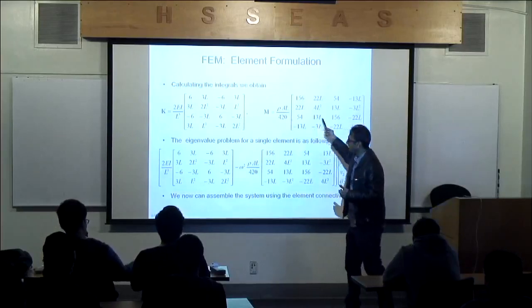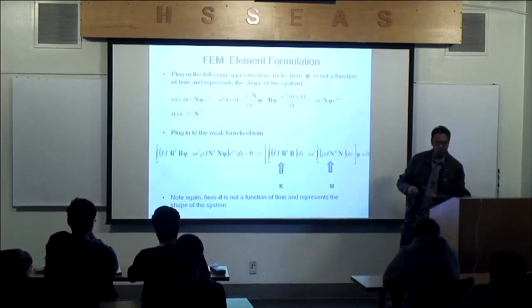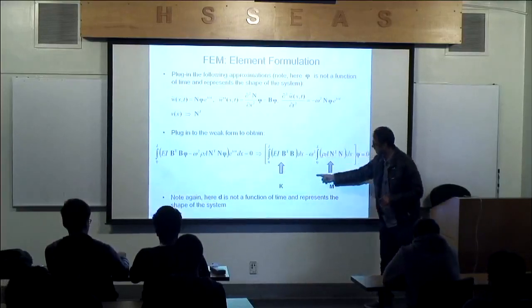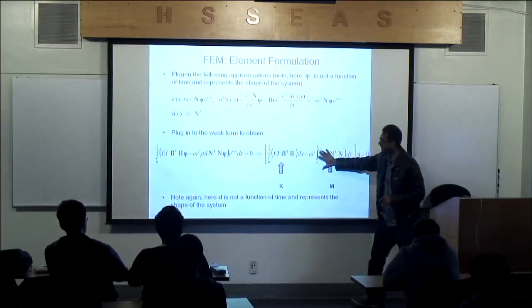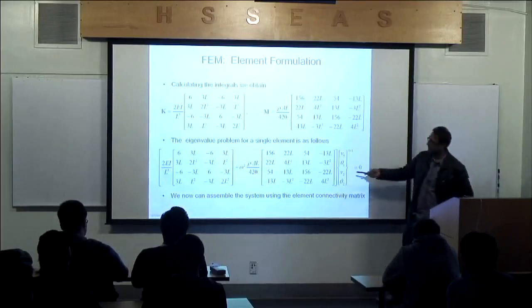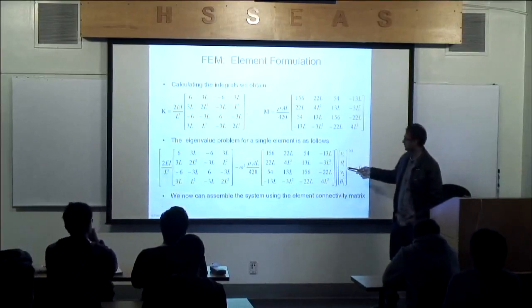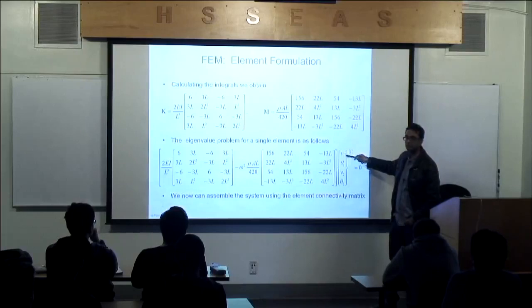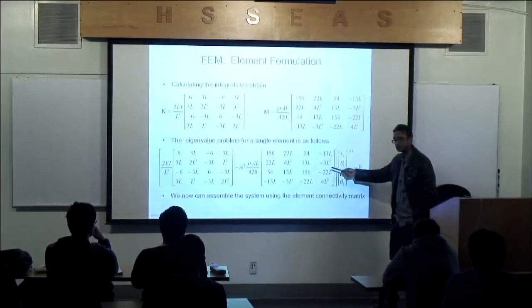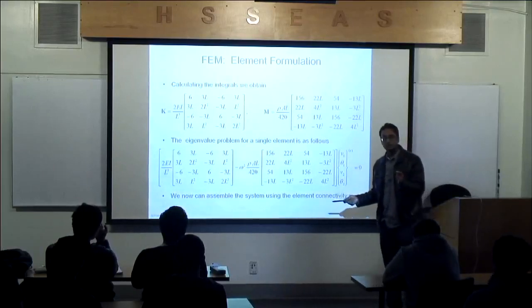So what if I plug that into my eigenvalue problem? Because in reality, if I have M bold and K bold, what I've done is evaluated this integral altogether. So that's K, and I've evaluated all that as M. So I have K minus omega squared times M, and so what I have now is this eigenvalue problem again. How do I know it's an eigenvalue problem? Because there's a trivial solution to this problem: v1 equals 0, theta 1 equals 0, v2 equals 0, theta 2 equals 0. If these are 0, the left-hand side equals the right-hand side, which is 0. But that's a trivial solution.